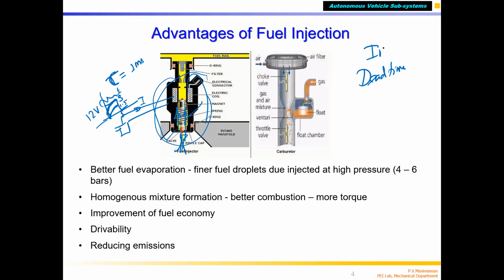But how do you know? You can test it by experiment. You can connect the injector to a 12 volt pulse using a pulse generator, which can generate a 12 volt pulse.